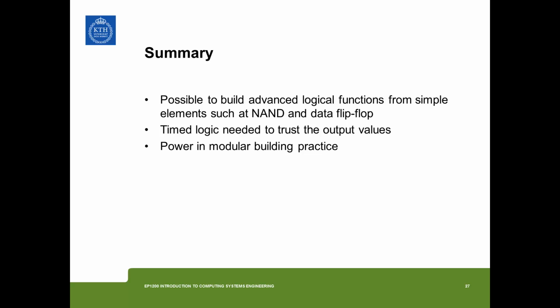Think, for instance, about building up the RAM. By first building a 1-bit register, putting them into a 16-bit register, and then from 16-bit registers building an 8-word RAM, and from 8-word RAMs up to 16K RAMs. You wouldn't like to build a 16K RAM out of data flip-flops directly.